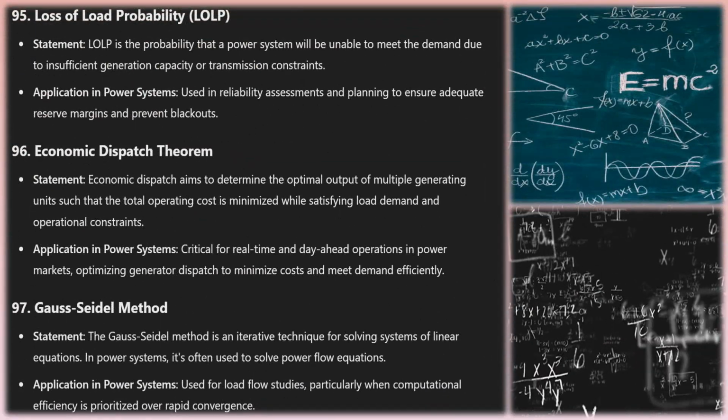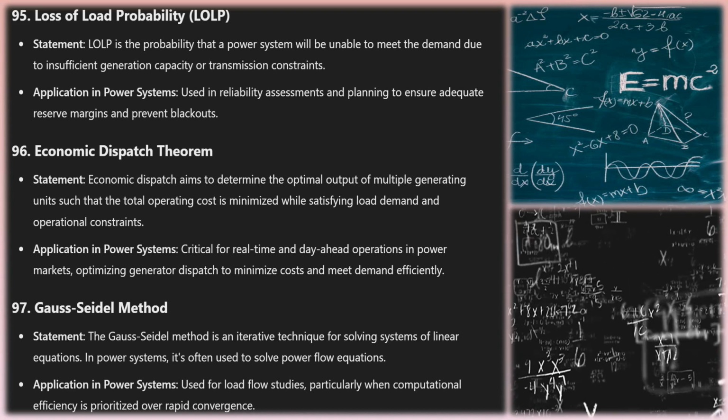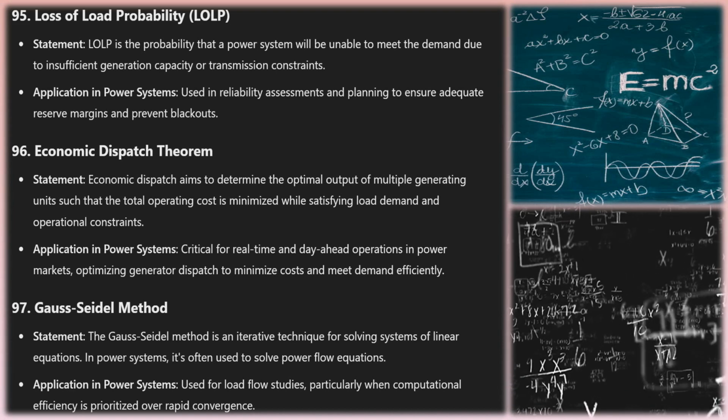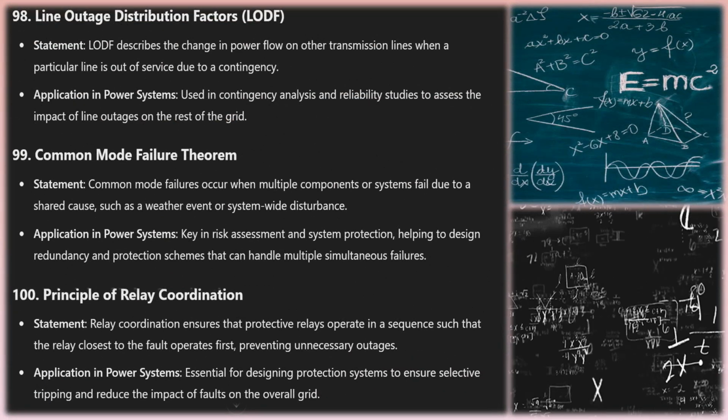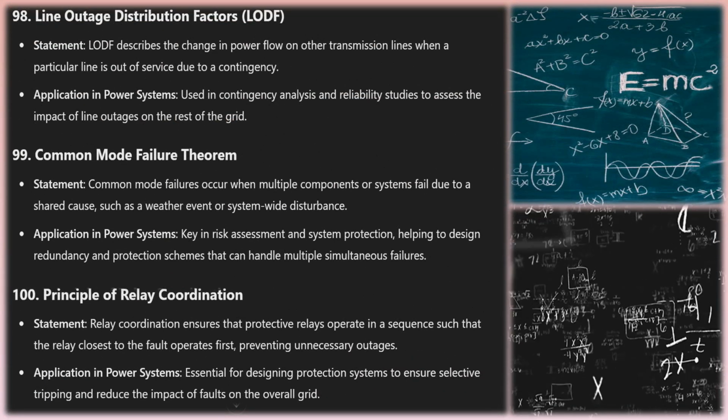Nodal admittance matrix YBUS theorem. The YBUS matrix relates bus currents to bus voltages in a power system, where each element represents the admittance between buses. Application in power systems: fundamental in load flow studies, fault analysis, and power system modeling.